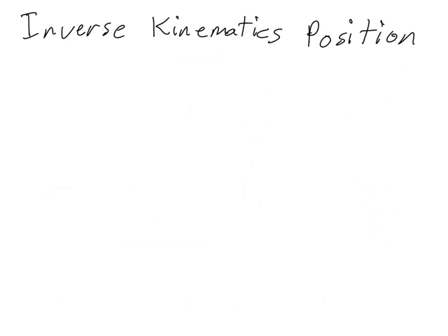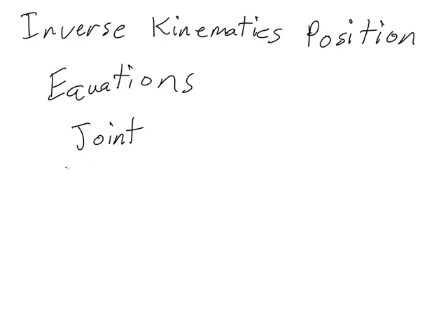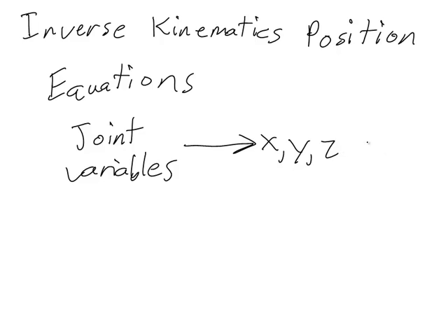In the position part of the inverse kinematics problem, we're trying to find some equations. And we want equations that relate the joint variables as inputs to the x, y, and z location of the end effector.